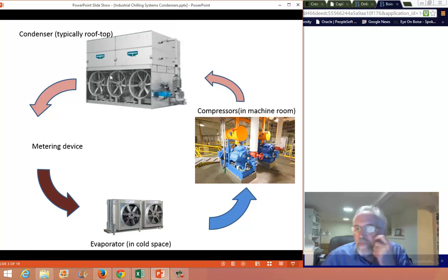And this is a typical rooftop unit. This is like a side draft evaporative cooler. The air gets sucked in here by these fans. If you look closely enough, you can see they're belt-driven fans. These are kind of old-fashioned. More and more we're going to designs where there are axial fans on the top with direct drive motors. But this is still pretty common. You'll see these all the time. The air gets sucked in here, blown out the top. Water's recirculated through this plumbing on the side. We'll talk more about that.